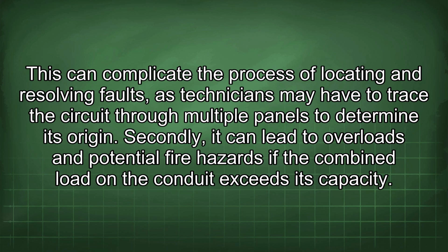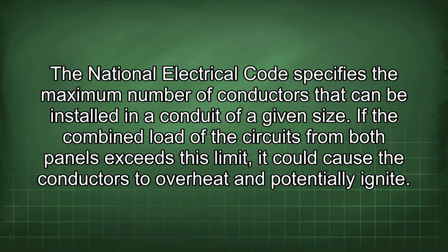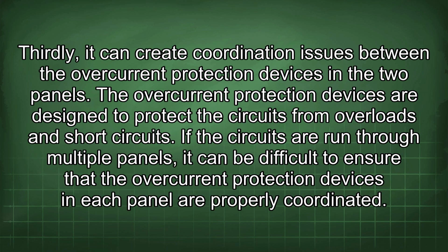Secondly, it can lead to overloads and potential fire hazards if the combined load in the conduit exceeds its capacity. The National Electrical Code specifies the maximum number of conductors that can be installed in a conduit of a given size. If the combined load of the circuits from both panels exceeds this limit, it could cause the conductors to overheat and potentially ignite.